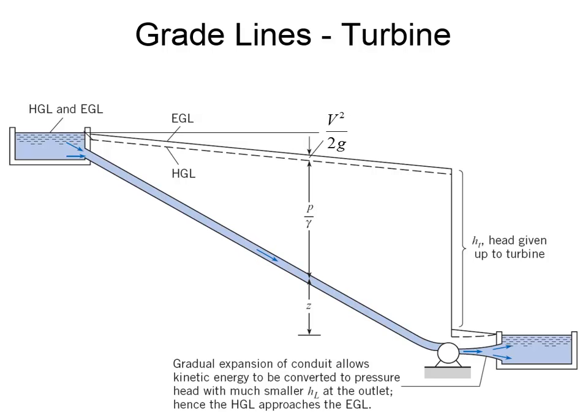And so when I say that the pump doesn't change the velocity, what I mean is that the pump doesn't change the velocity of water in the pipe. But of course, the pump will change the velocity of water through the pipe compared to if there was no pump. But the way the pump works is not by increasing the velocity. The way the pump works is by boosting the pressure on the outlet side of the pump. So it's important to distinguish between those two.